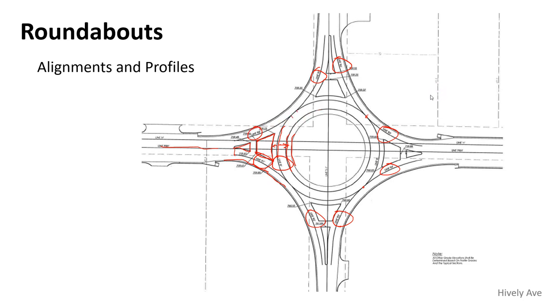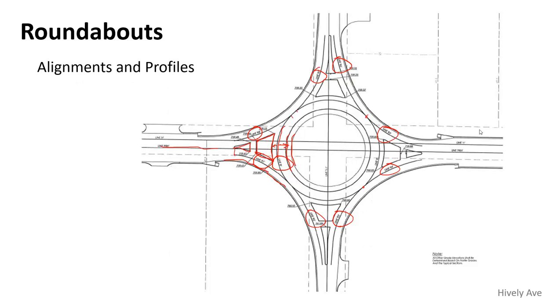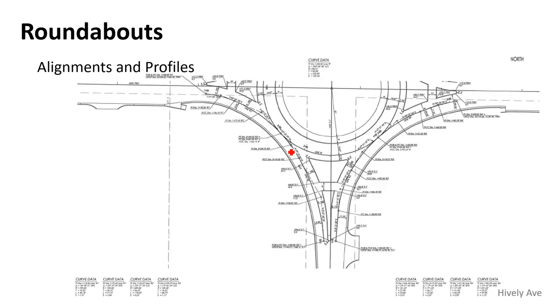So that's one example of how to design roundabouts. The reason you make this an alignment and also have a profile for it for elevation is to make sure it's super smooth. That's the whole point, to make sure there's a super smooth transition through here for vehicles as they come through. And so that's the overall look at it. And this was actually calling out where the splitter islands were in some elevations, right? This is actually what the alignments look like coming through there.